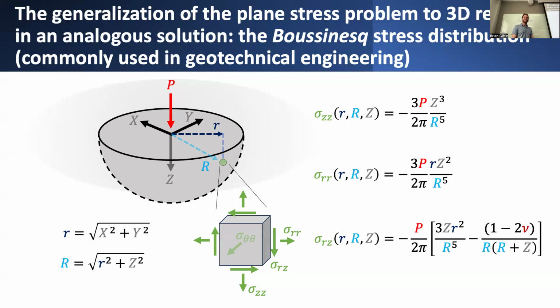So particularly in the case of soils, you're really interested in not just how much compressive stress can the soil sustain. Well, that's definitely useful to know, but it's not the whole story. And especially if you're trying to design for the bearing capacity of a soil, you also have some other modes of failure. What's a particular mode of failure that you're concerned about when it comes to assessing the bearing capacity of soil? Shear.